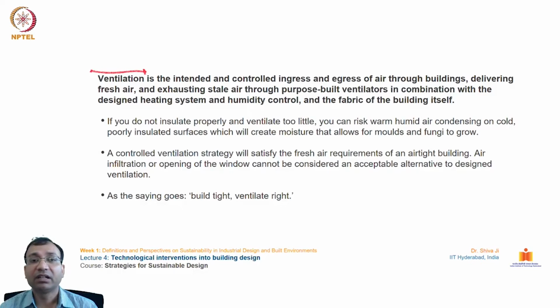So we have to check such things, which in turn will further give rise to the growth of mold and fungi in the interior spaces, and which can further cause damage to the health of the occupants. The next one talks about a controlled ventilation strategy that will satisfy the fresh air requirements of an airtight building. Air infiltration or opening of the window cannot be considered an acceptable alternative to the design ventilation. Okay, the last one, as the saying goes, build tight, ventilate right.